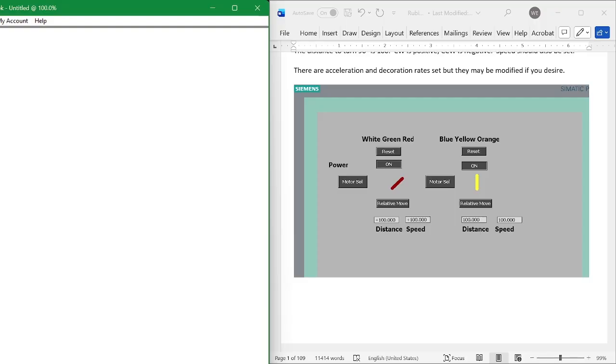And you multiplex the signals to the 3 because you can only spin one at a time, and I only had 10 outputs, but you dedicate 2 outputs to the actual motor and 3 to the direction and 1 to the left or right. So basically you have 2 relative move instructions in your program to start out with. And this is just so that you can prove that it runs and to set up the motors.